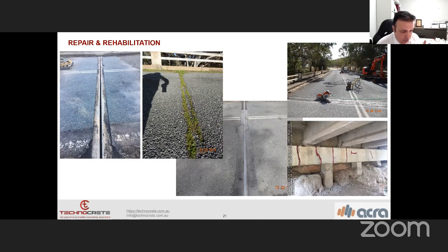The most important problem with that bridge started with water leaking through the deck joints, from the expansion joints. Because they used high silicate aggregate, moisture can accelerate the ASR reactions. The deterioration rate of ASR can be accelerated by increasing the temperature and increasing the moisture available. Water could easily penetrate through the expansion joint and reach the pier and crosshead of the bridge, and then the deterioration which we saw.